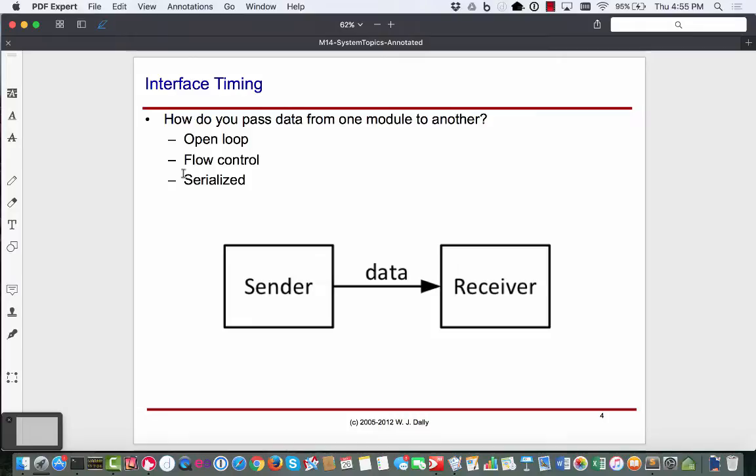One of the costly things around hardware is I can move lots of data within the chip, but for data to go outside the chip, it has to go through pins, something mechanical. And all those pins, which are sitting at the periphery of the chip, or connectors on your boards, take area, they take volume, they are sparse, so they present a lot of challenges.